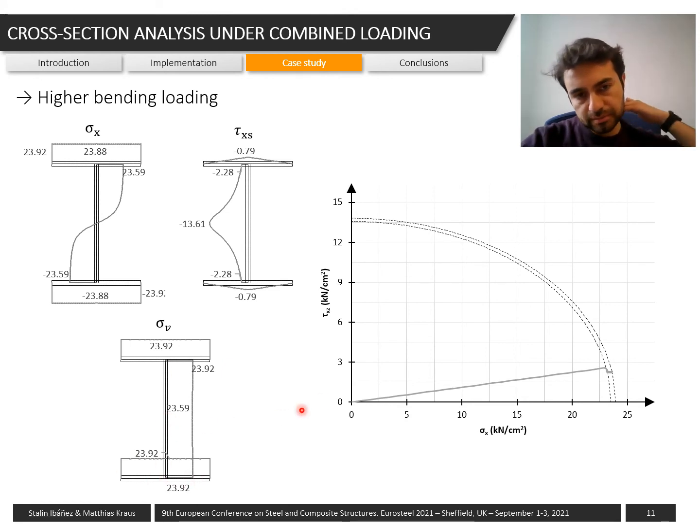Here you can see the equivalent stresses of the whole section, in which every part of the section is plasticized. When we take just one specific point of the section, for example, this fiber here in the upper side of the web, we can analyze how the stress path looks with respect to the shear stresses and the axial stresses. We see how when we reach plasticization, the stresses somehow accommodate a bit along the yielding surface, and then they start to increase again up to the next step in the hardening part of the yielding.